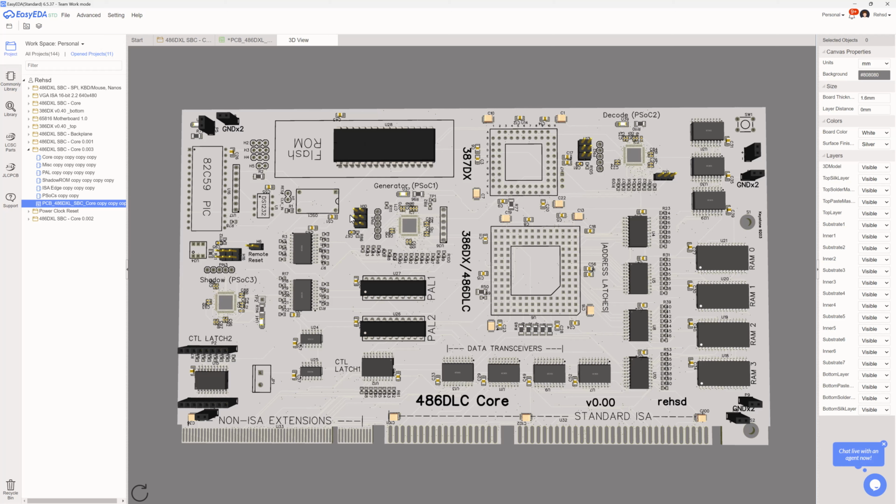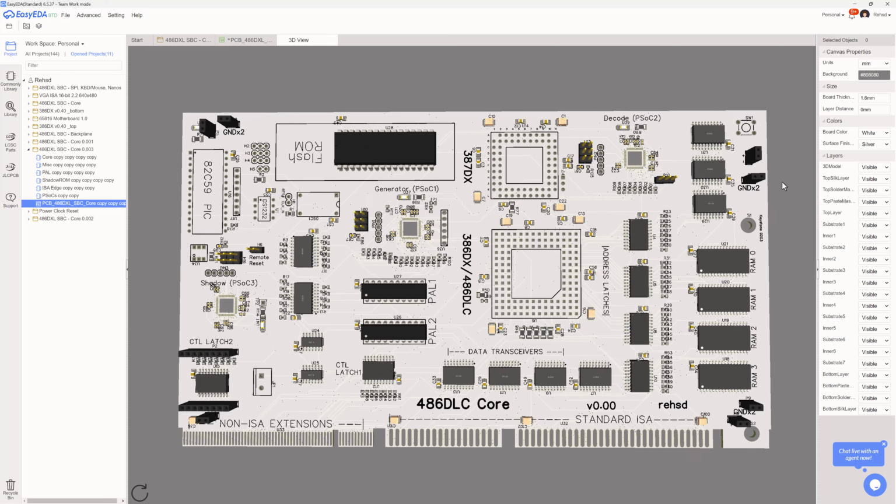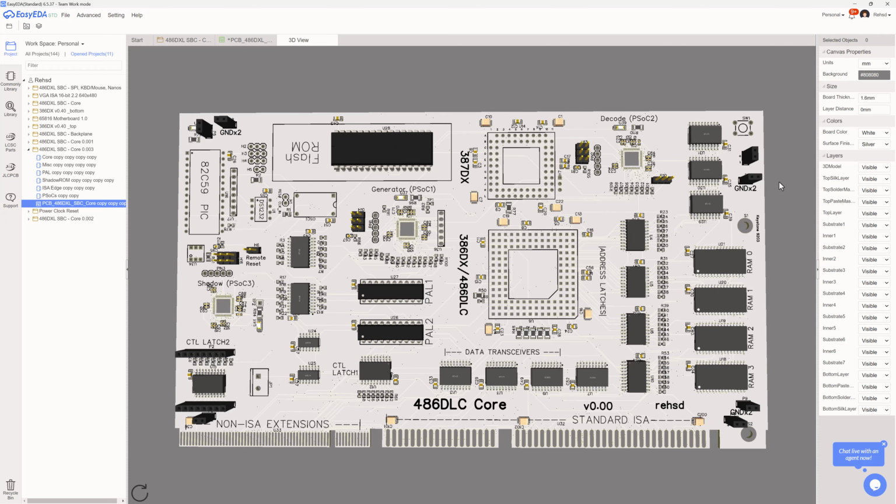And I'm going to see if I can get that down to a 6 layer or maybe even a 4 layer if I leave it spread out a bit. And I'm going to have to do a bunch of manual routing work with the PSOC right away just to see if I can help the auto router get through it. Again, trying to just simply validate that I can get it auto routed or 80% auto routed in general. And then if I can turn around and maybe do some better work on a manual side as I try to learn how to do that decently.